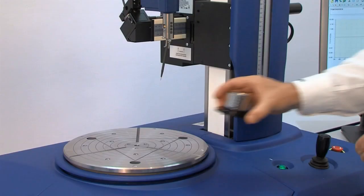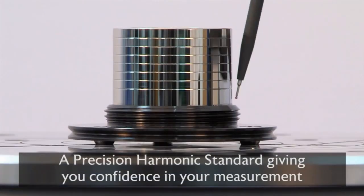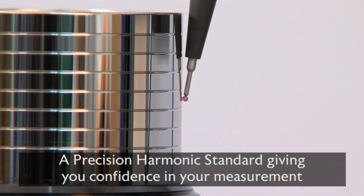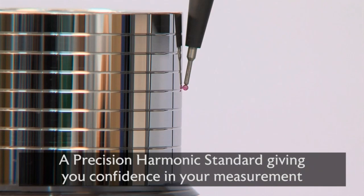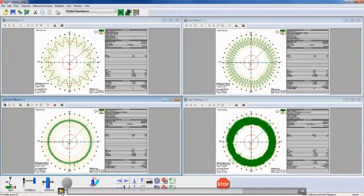So we've got the harmonic standard here being measured. If I stop there, we can see the different bands, the results from the different bands here, and we can check the values of the harmonics, either having a look here, in this particular case, at what the results look like, but also looking in the histogram to see that the values match the certificate.